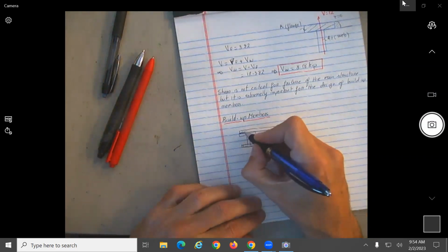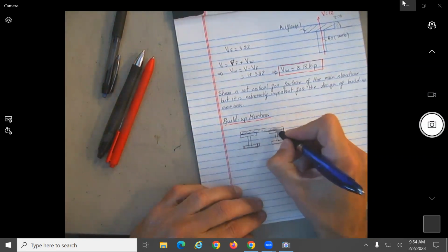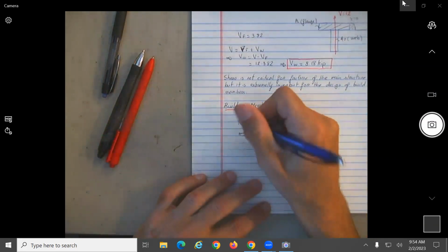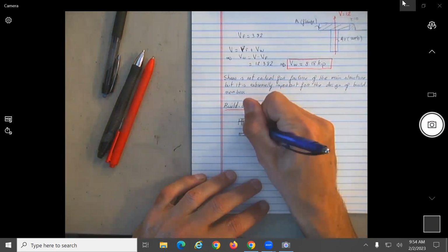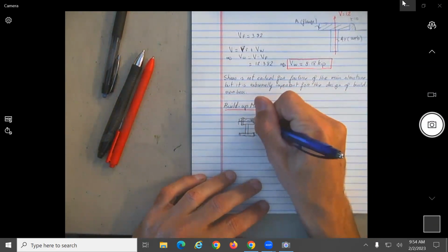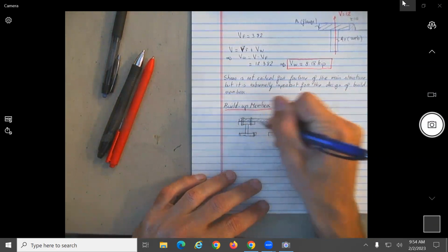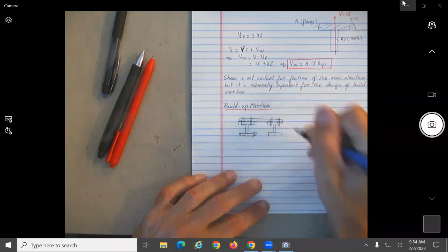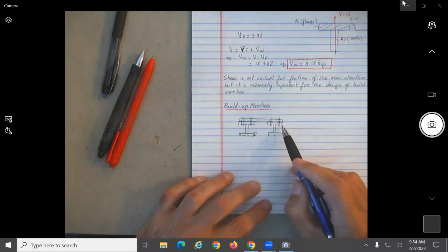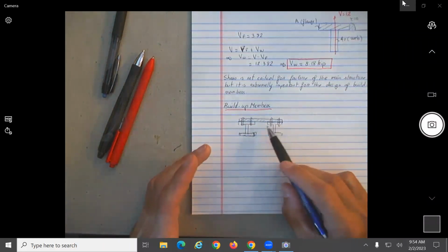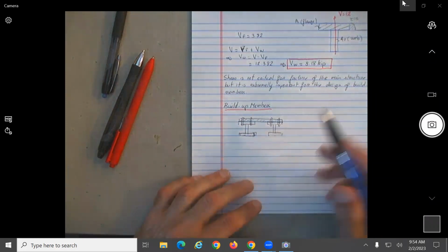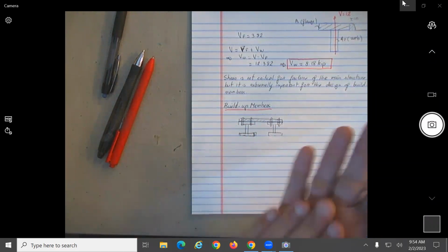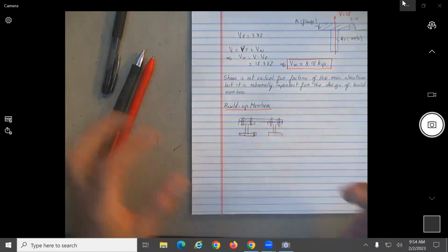Okay, so for example, you will probably have to use bolts over here, or rivets, whatever you want. So what should be the diameter of each one of the rivets or the bolts in order to resist the load, or how many of them will you need, no? For the plate to stay on it and not come off the structure when it's bending.